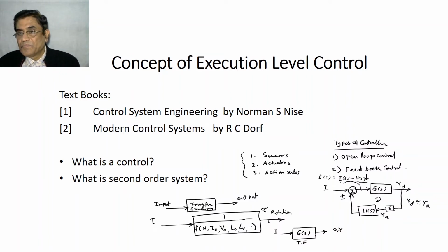And this error has to be compensated. Error is a signal, and according to that error signal, if it's big or small, we take different kinds of action. Those are called control action. There are various kinds of control action, and we will talk about those in robotics. The most prevalent ones are PD and PID, proportional derivative, and proportional integral derivative. Proportional to what? Proportional to error. Integration of what? Integration of error. D is what? Derivative of the error, the rate of change of the error.